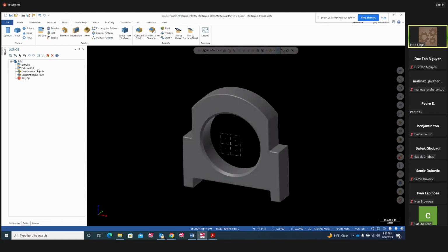What we will do, I'm going to just go ahead and delete that and regenerate. If you delete anything, the solid turns a red cross. You see this here? That means this is your dirty operation, so you have to regenerate. There you go.